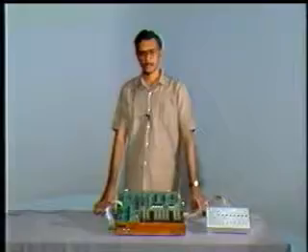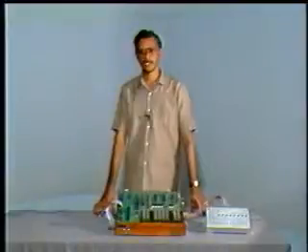Again, consider a washing machine. The 8255 can be made to read different parameters such as water temperature and water level, and it can be made to switch on and off relays and pumps. Again, mode 0 is very much suited for this application. Having learned the details of 8255, let us view a demonstration in which external devices are connected to 8255.